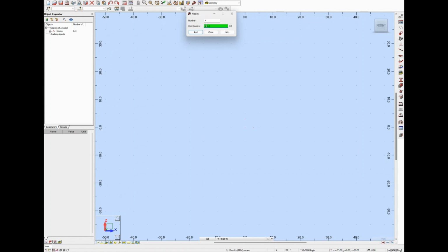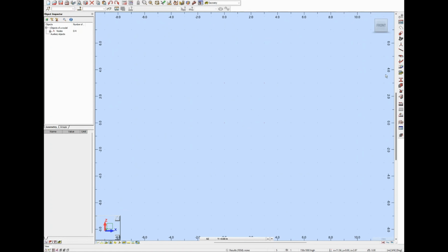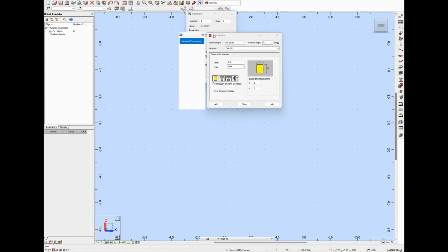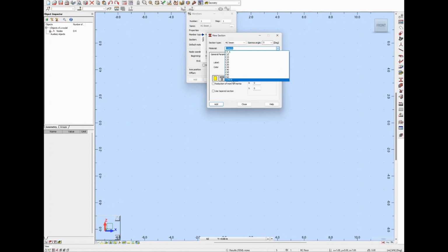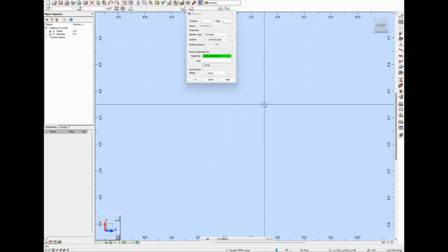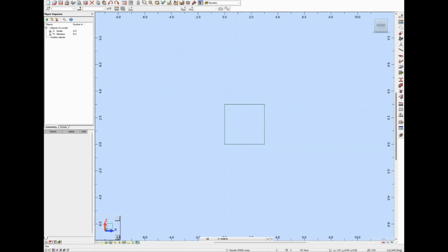I'm popping in the nodes X, Y and Z. So here you can see the 4 nodes. Okay, we use our line beams and we're just picking an RC beam and we're making sure we're picking our concrete. So a drop down menu, C40, C50, whatever you want to pick. And then we pick it that it's going to have a design per meter weight, and we're going to have a 300mm thick wall, while 250 will be more common for a 3x3 culvert. Okay, so we're just clicking between our points, and there we have it, we have our box.